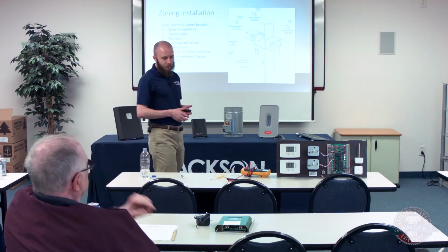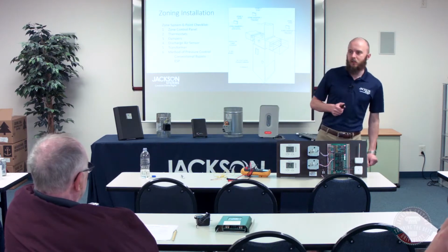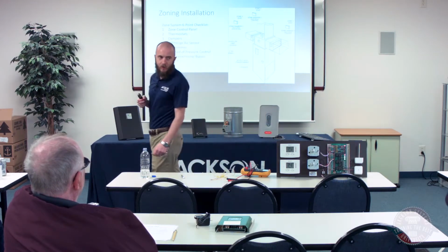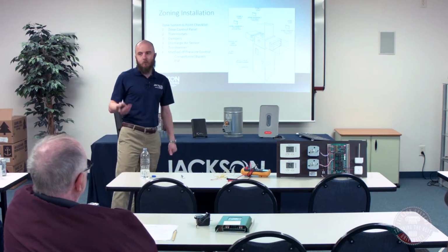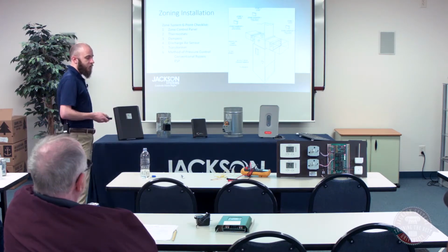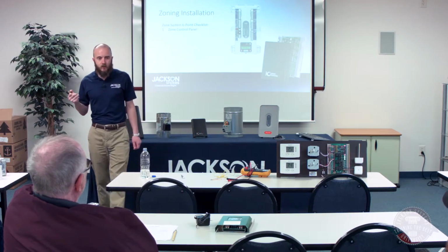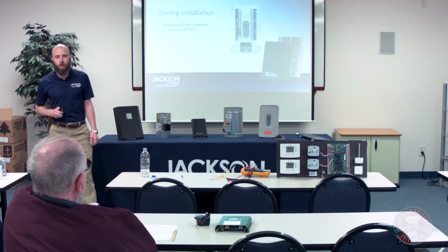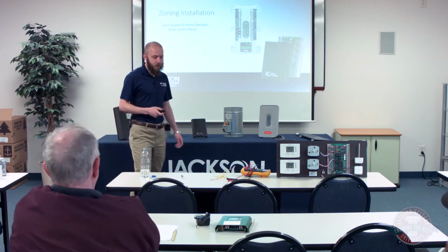So your first step here, this is for any zoning installation. We tell our sales guys here in the office we have this 6-point checklist. We always make sure that you have ready when you're doing a zoning, basically, the parts and components you're going to need for a zoning project. So number one, obviously, is the zone control panel. This is going to be the brains of the operation. Whether it's one of the I/O HVAC controls panels or Honeywell panel or whatever you use, you got to have something there to control the whole operation.